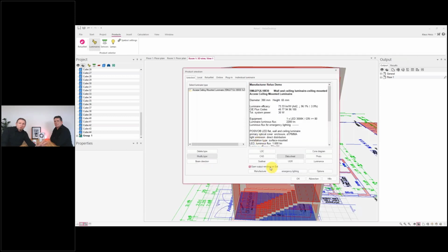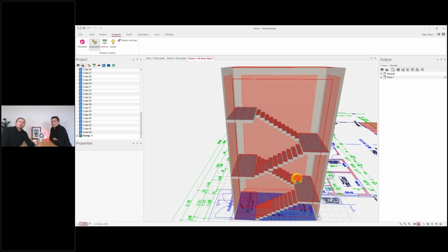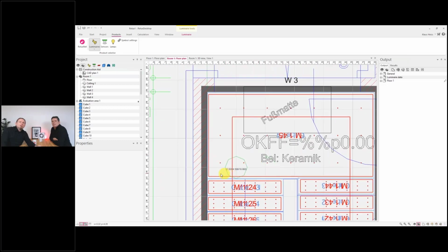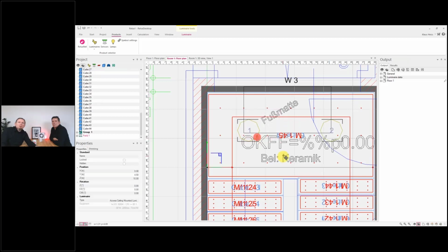Yeah, so it's possible to modify luminaires, but in the output you end up with a mark on it. It's marked as modified. So now we need to put the luminaires in, and I'm starting this also in 2D, not by creating single ones. I want to have them in fields because I know I need 2 of these luminaires, 2 in a row, room orientated, something like this.